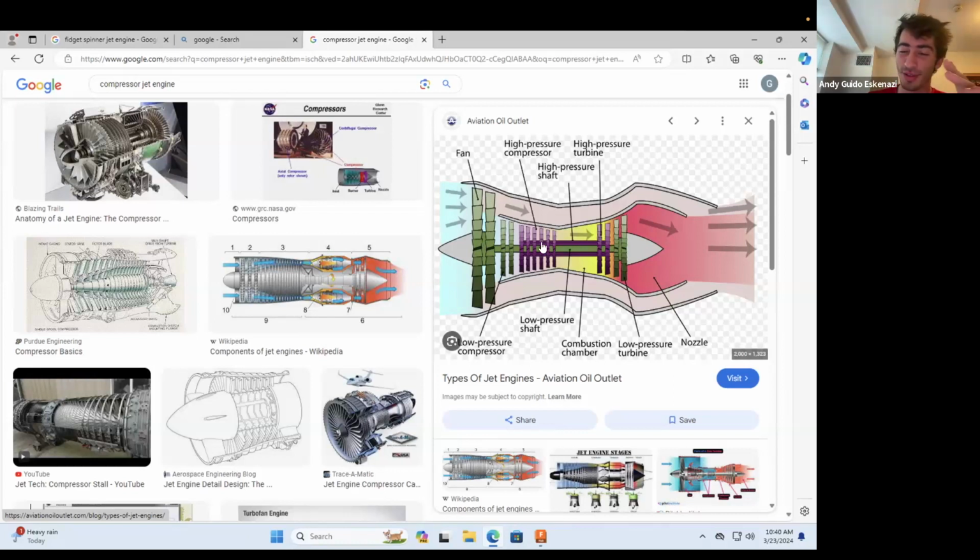Maybe the schematic is not the best one, but in essence, it's this stuff in here. That's what we call the core. And it's the core that actually drives the fan, and it's the fan that then moves all of the air through the bypass stream to generate the thrust. So then air goes here through the compressor, and that essentially brings the pressure of the air from the atmospheric pressure to a very, very high pressure, maybe 30 times as high. And then you go over to the combustor.